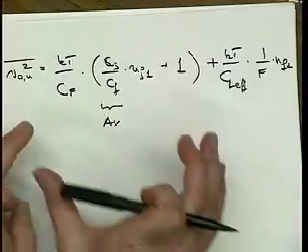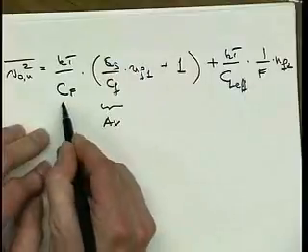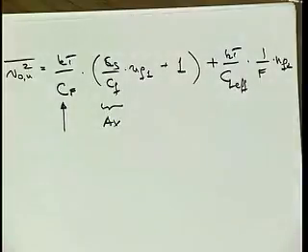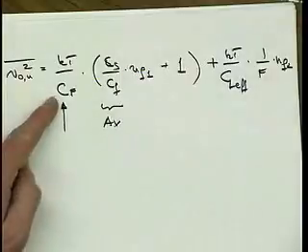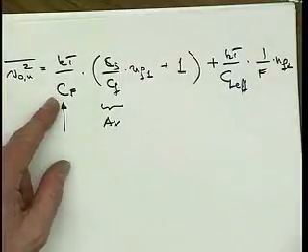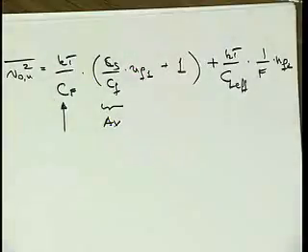So this also says other interesting things. There are all sorts of considerations for choosing the value of CF. But one of them, of course, is that if we make CF too small, then we get a lot of extra noise, just like the feedback resistors, right? Noise is one consideration.